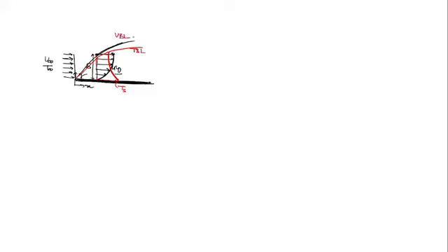Now, the thickness of the thermal boundary layer may be equal to the velocity boundary layer, may be more than the velocity boundary layer, anything is possible. That depends upon the property called thermal diffusivity. Because just as I told you, a thermal disturbance takes place on the wall, on the surface of the plate, yes or no? Just like the momentum disturbance has taken place, similarly here a thermal disturbance has taken place.